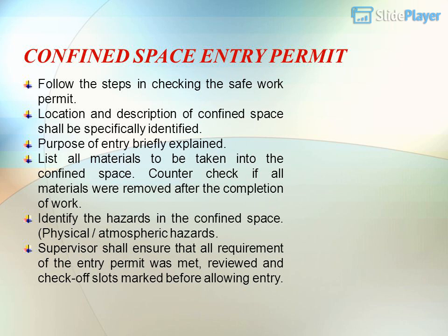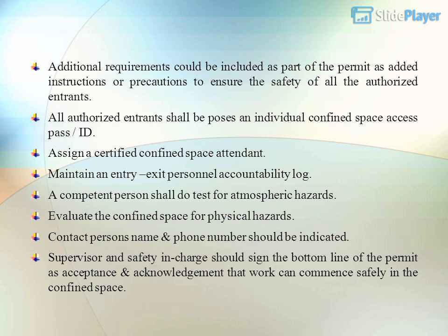Identify the hazards in the confined space: physical and atmospheric hazards. Supervisor shall ensure that all requirements of the entry permit were met, reviewed and check-off slots marked before allowing entry. Additional requirements could be included as part of the permit as added instructions or precautions to ensure the safety of all the authorized entrants.